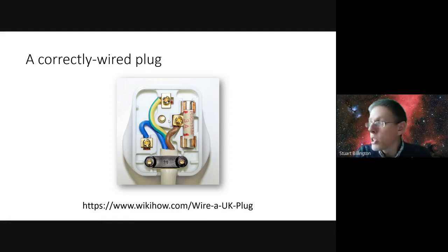And then if you were to trip over a cable and hoik some of these wires out of the holders that they're in, you could end up with live wires flapping around all over the place. So there's this cable grip here, which literally grips the cable, not the wires, the cable, this little white bit sticking all the way through the cable grip. And that's making sure that if anyone trips over the cable, they're not going to accidentally pull any wires out of the plug.